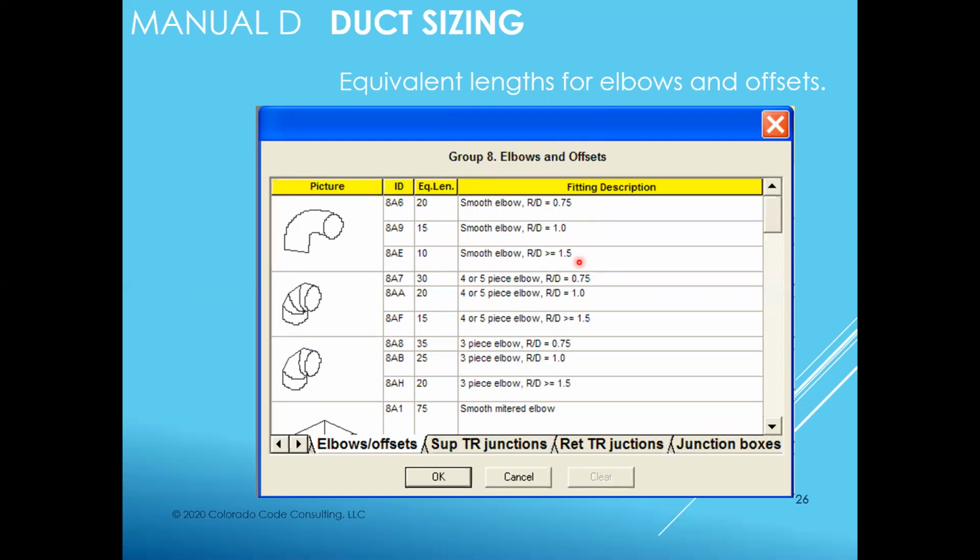Woo. So if this were a 6-inch duct from here, a 6-inch 90, this is a one-piece stamped 90, one of the finer fittings that you can get. This would not fit in a joist bay in any way, shape, or form, right? From here to here, there's probably close to 16 inches. It's gigantic, right? What do you suppose we are normally seeing?